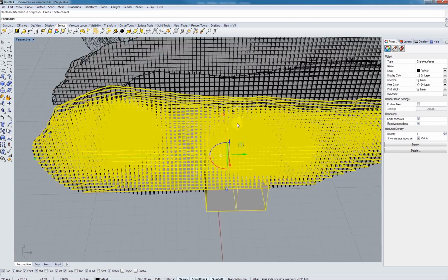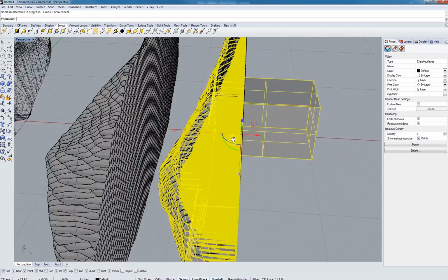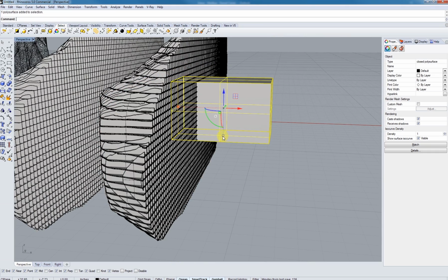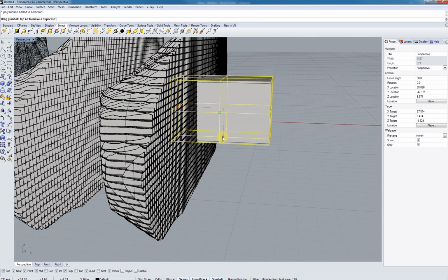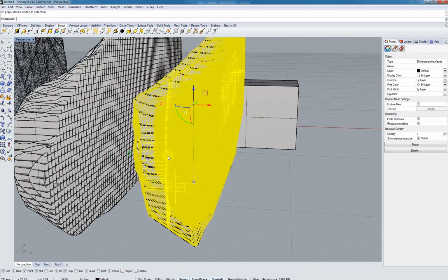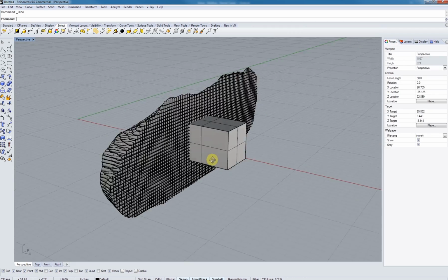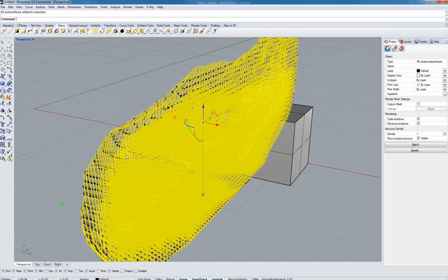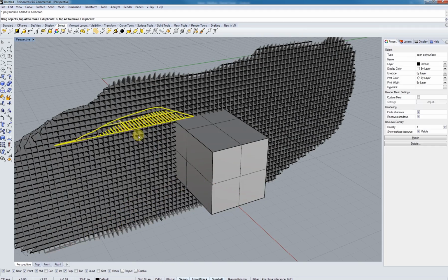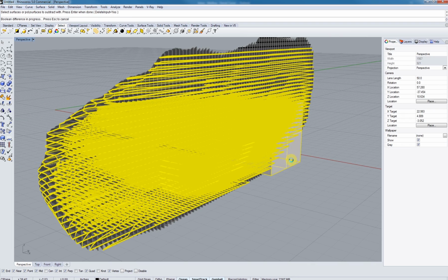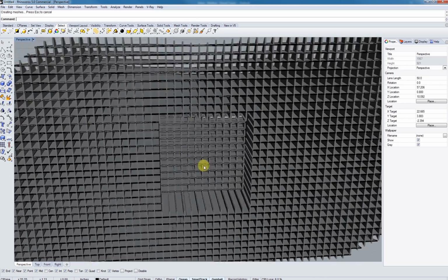So it looks like this is a little bit of a tight fit. So what I'm going to do is scale it so it fits in the middle. I might just hide these guys so it makes it a little easier to visualize. And then I'll lock these guys down. And I'm just going to take these and Boolean subtract one more time. This might be a little easier on it. Sometimes on Booleans, when you have faces directly on faces, it doesn't Boolean out too well, so that's why I scaled it in one direction. So there we are.